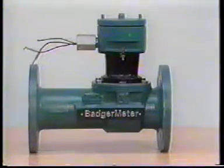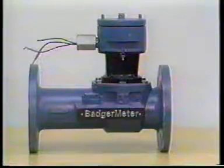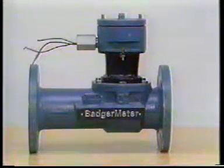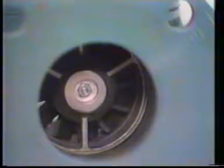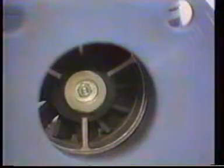Let's begin with the meter that measures the velocity of fluid flow to determine flow rate, a current type flow meter. In this case, we're referring to fluid current, not electrical current. Current type flow meters infer flow rate by the reaction of the fluid on a propeller or turbine. Current type flow meters that are installed in a pipeline are called turbine flow meters, and that's the type we'll look at.